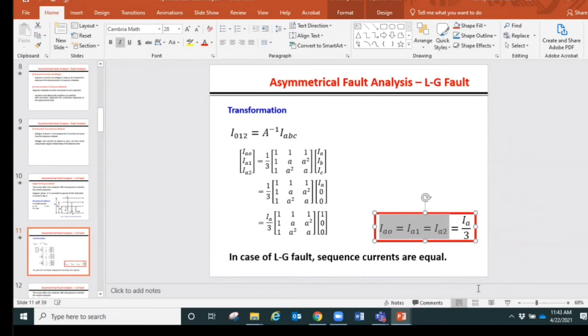We go back to what we were just discussing in terms of series parallel connection. So the positive sequence network, negative sequence network and zero sequence networks are supposed to be connected in series. Is that clear now? So we'll draw the three sequence networks and those three sequence networks in their reduced form. Reduced form means, if you remember in power systems 1, we were drawing the reactance diagram and then we had to finally reduce the network to a situation where we will have only one voltage and one impedance. Then we can calculate the current easily. The same thing will happen here.